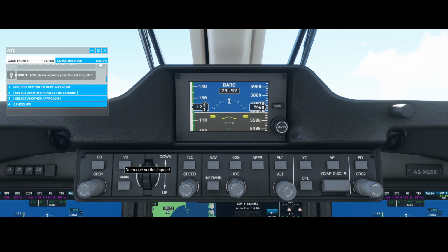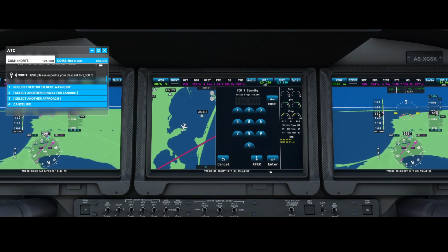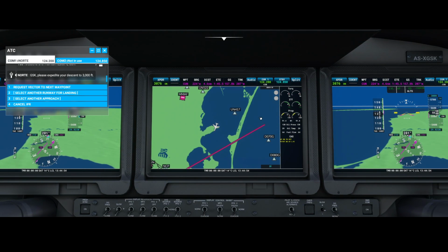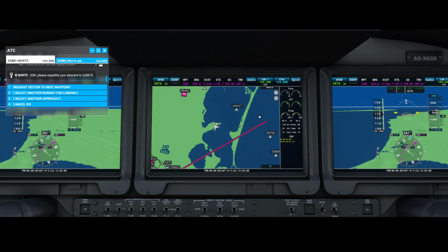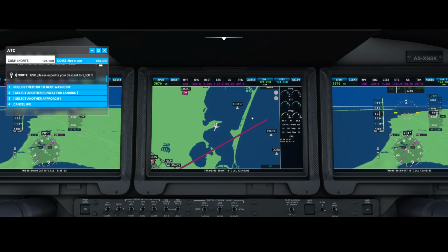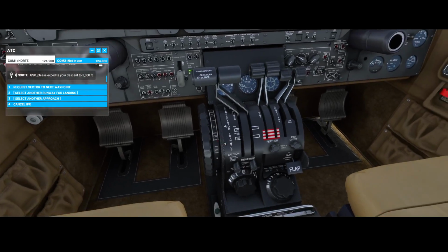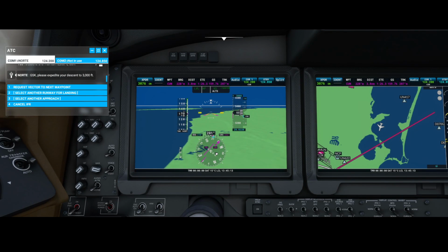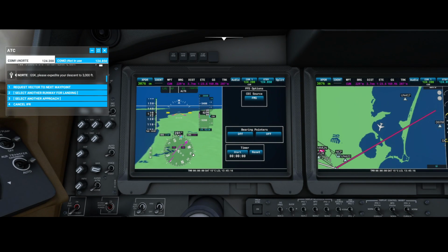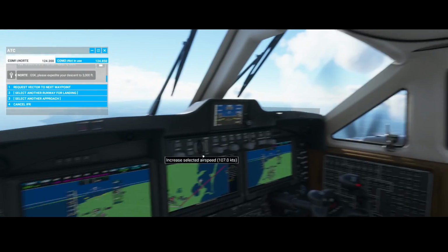Yes, we're descending. And in the meantime, we're gonna pull back the throttle a bit. And cancel here. And we're almost at the pink line, right? So by setting the option to the navigation system to nav, and by switching the CDI source to FMS, that's all the things we needed to do to make sure that we're following the pink line.